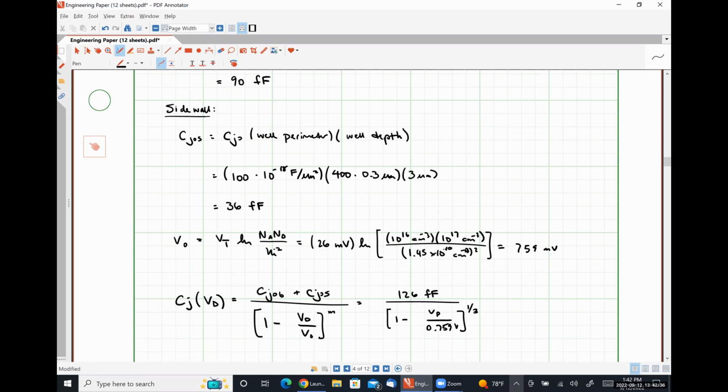So we still haven't finished all of our N-well notes. We're getting very close though. We only have 2.5 minutes left of class, so this is where we're going to stop for the day. What we're going to talk about in the next class meeting is a combination of these two things. We have observed that our N-well material inherently behaves like a resistor. If we apply a voltage to our N-well material, it also exhibits some sort of capacitance.